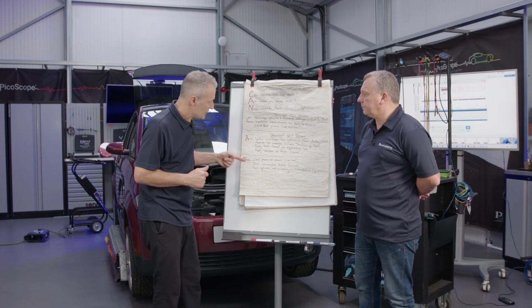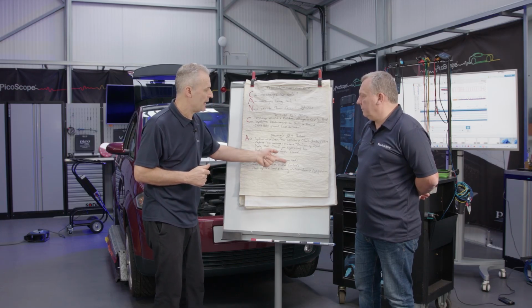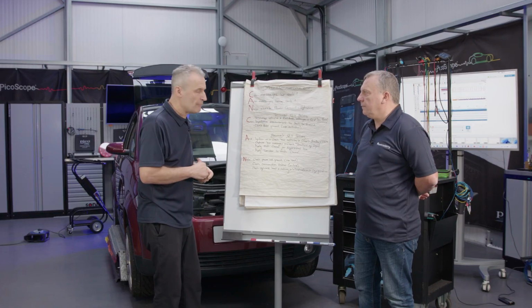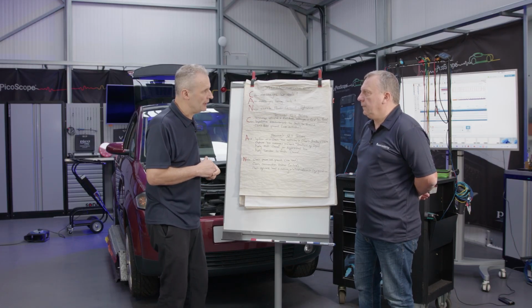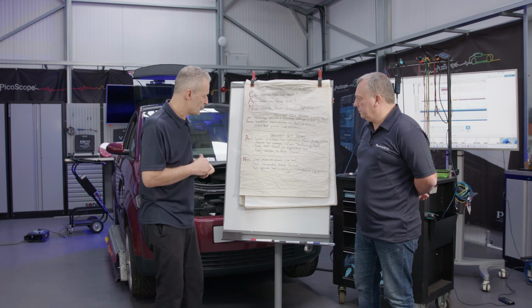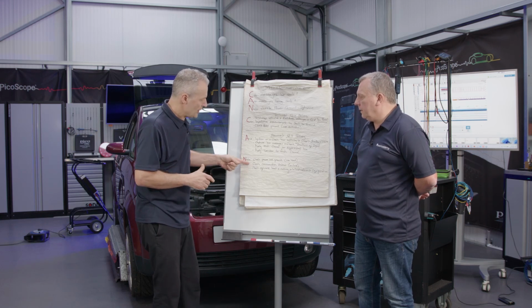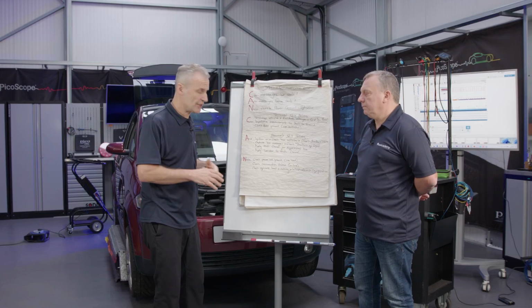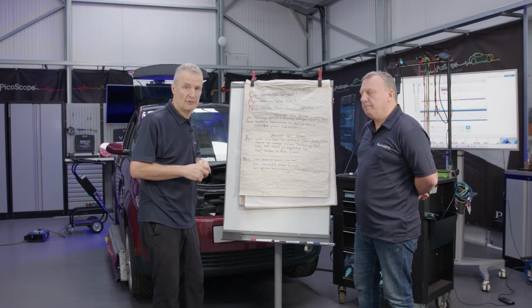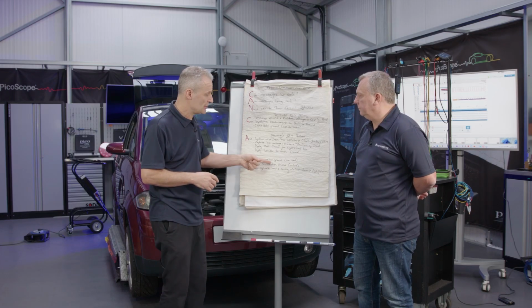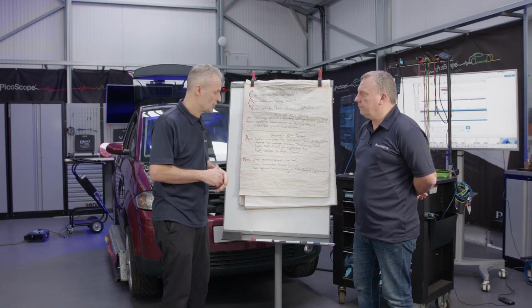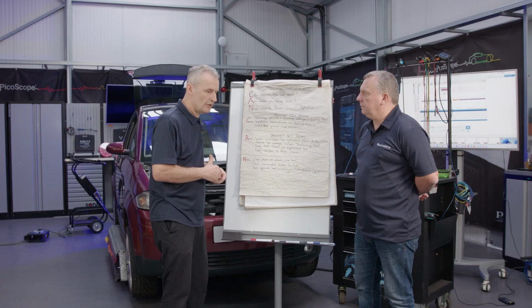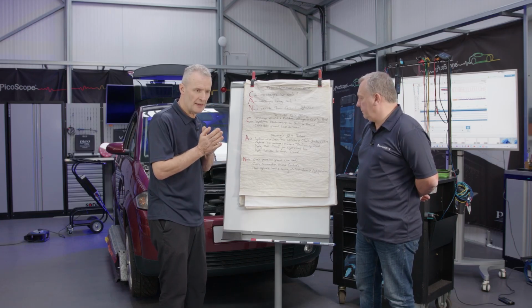Apply decoder, and then the next is the node, isn't it? This is just power and ground because we had a communication error. Remember to load the circuit, that's the key. Yeah. Power, ground, voltage drop. Check communication status. Is the device online? Can it physically be seen with the scan tool? And check the software level coding. It might be that all of this is okay, it just simply is not initialized, configured, or configuration for the vehicle. I'm trying to think of the other terminology.